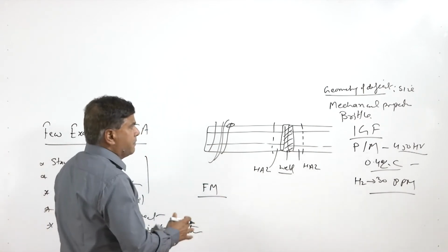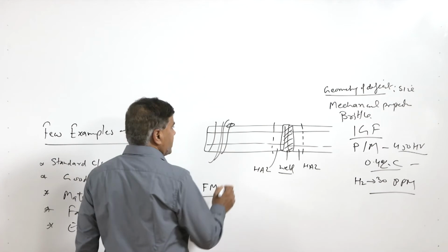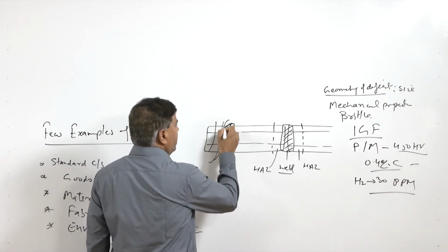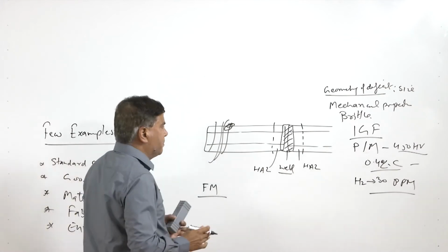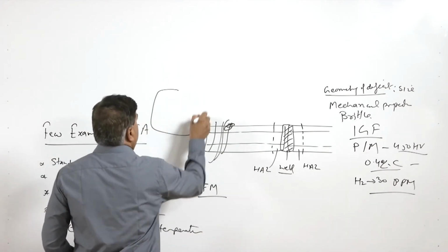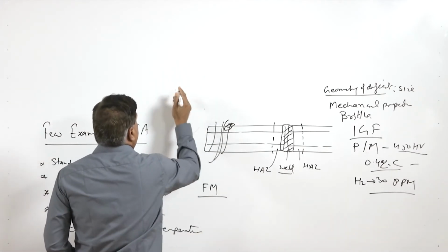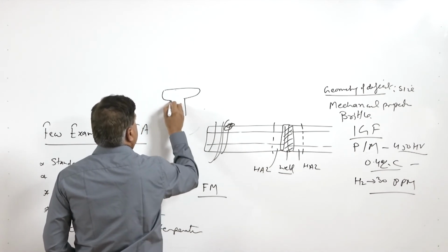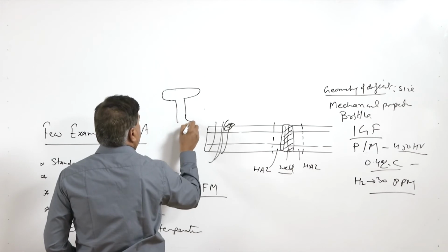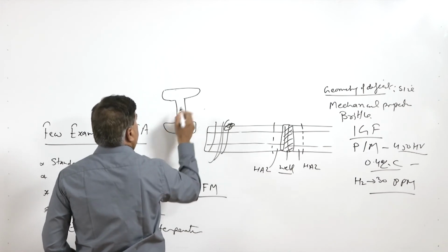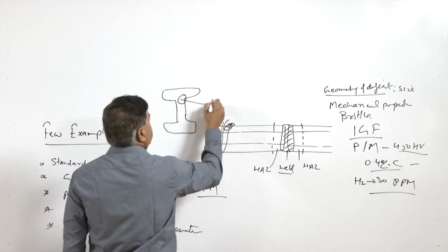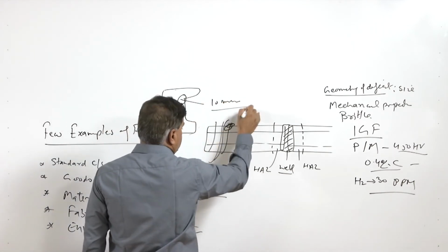and after that we can do the fracture mechanics analysis, and the fracture mechanics analysis may suggest that there was some kind of crack present, because the fracture surface showed that in the rail like this, there was a crack which was present, and this was dull, and this crack was especially present in this area of say 10 mm size.